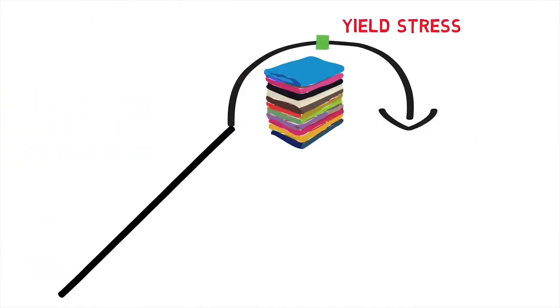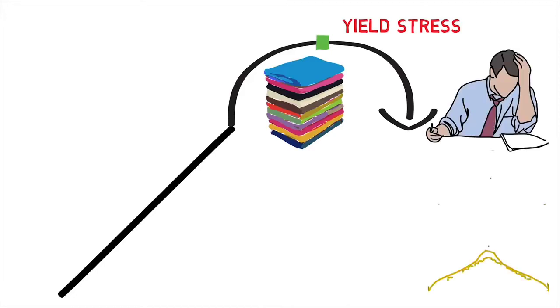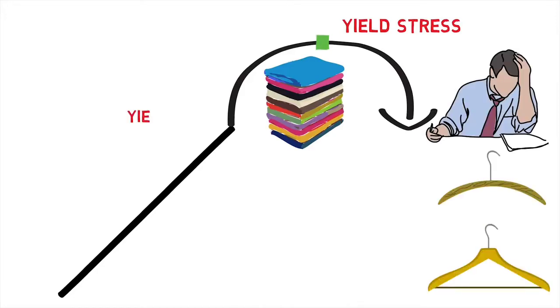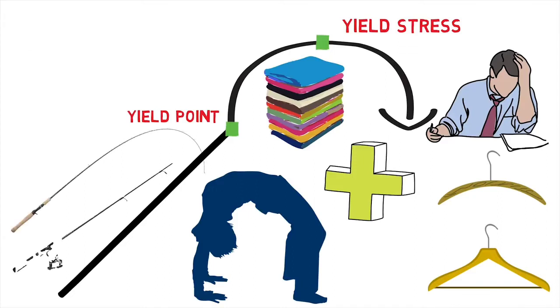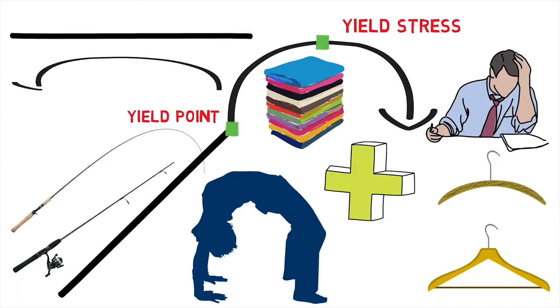Yield strength or yield stress is the material property defined as a stress at which a material begins to deform plastically, whereas yield point is the point where non-linear, that is elastic and plastic, deformation begins. Prior to the yield point, the material will deform elastically and will return to its original shape when the applied stress is removed. Once the yield point is passed, however, some fraction of the deformation will be permanent and non-reversible.